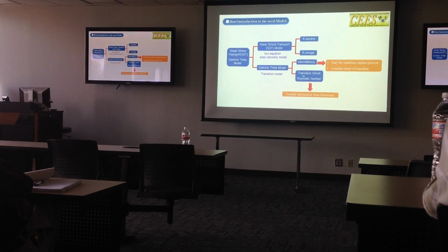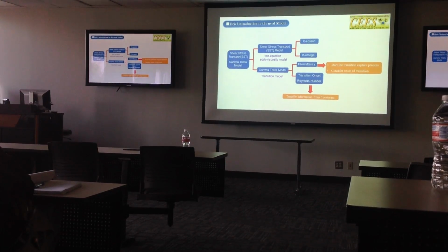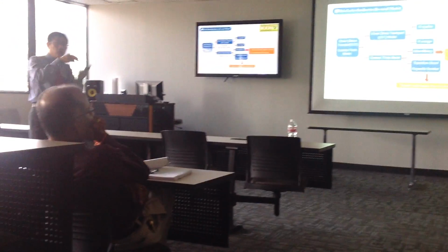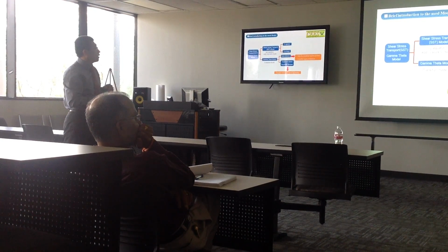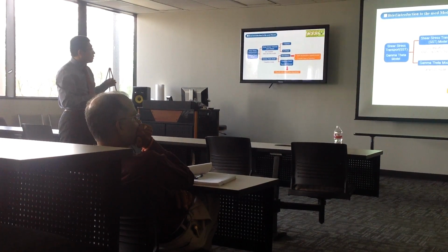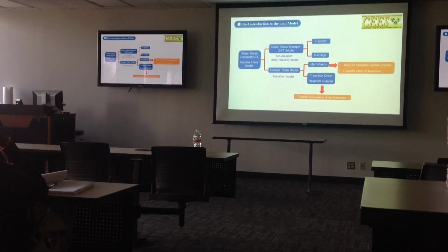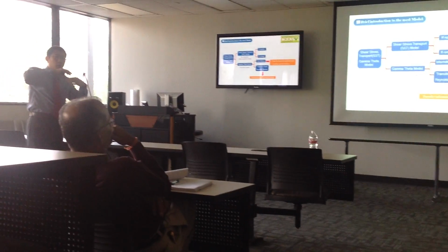There are two main important parameters there. They are intermittency and the transition onset Reynolds number. The first parameter is used to start the process in this model to capture the transition flow, or we can say it considers the onset of the transition. And the other parameter is mainly used to transfer the information from the free stream to the boundary wall. That's the function.